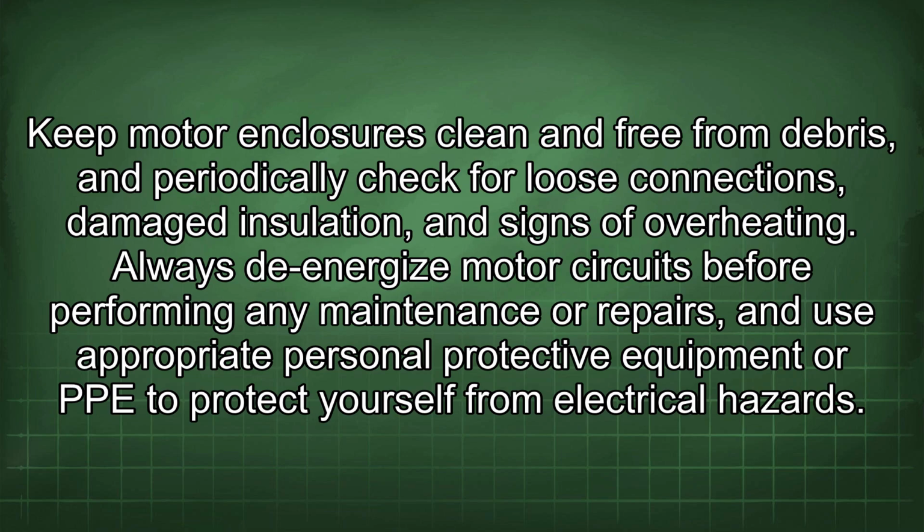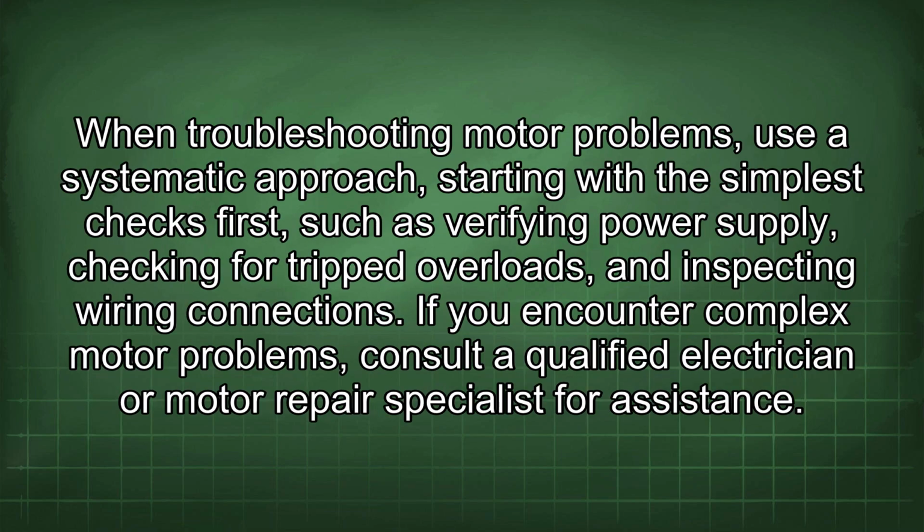Always de-energize motor circuits before performing any maintenance or repairs, and use appropriate personal protective equipment or PPE to protect yourself from electrical hazards. When troubleshooting motor problems, use a systematic approach, starting with the simplest checks first, such as verifying power supply, checking for tripped overloads, and inspecting wiring connections.